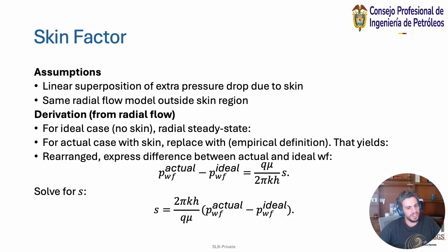So what is the purpose of the skin factor? It is one of the most powerful indicators of our well integrity, right? This is how good our well conditions are. There are guidelines on what you can say, but you can also use the skin factor to account for near wellbore effects in pressure transient testing or well testing. This is used quite a bit when you're trying to do inflow performance curves in your PTT analysis.